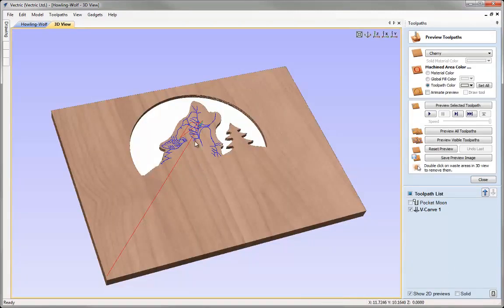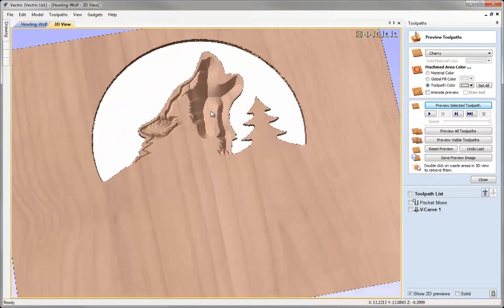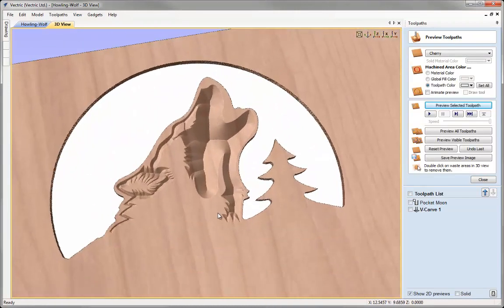Now we can see what that's going to give us here in the 3D view, and we can also preview the selected toolpath there. And if we look at that result, we can see it's not really what I'm looking for in this case. The software is just going to calculate a point based on the angle of the tool all the way to the center of the area of that selected set of vectors. That's given me a slightly odd looking result. What I'd really rather have is the same kind of angled edge, but I'd like it to flatten off in the bottom of that pocket and not go so deep.